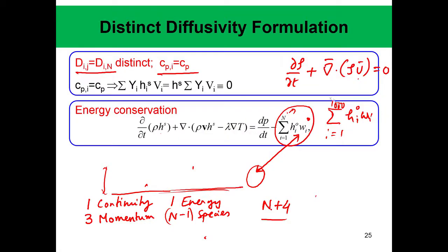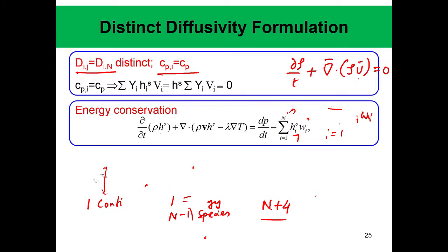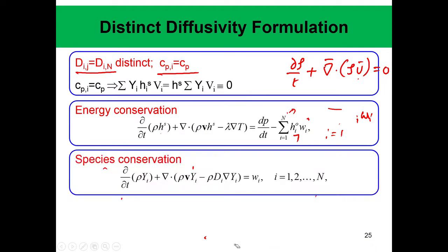So, once again going back to this, if you are talking about the energy equation, you have on the right hand side this total heat release rate, and this heat release rate contains the species production rate and the species consumption rate, which of course contain temperature, but also the species mass fractions, right.